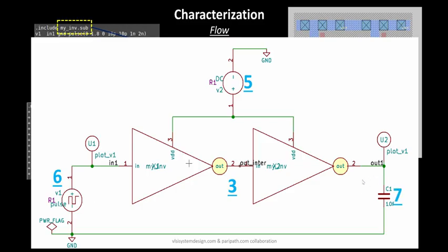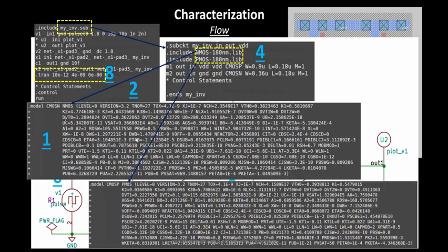Next you have to provide the necessary output capacitances. So over here I have given an output load capacitance of 10 femtofarad, and this has to be varied. For example, if you look into non-linear delay models or NLDM, the output capacitance is varied in a range. So that's what we have to do. So let's say for a simple setup, we are going to look into a fixed capacitance and figure out what the characterization behavior looks like. And then finally we have the 8th step, which is that you need to provide the necessary simulation command. So over here we are doing a transient simulation, so we give .tran. If you do a DC simulation, we have to give .dc and so on.